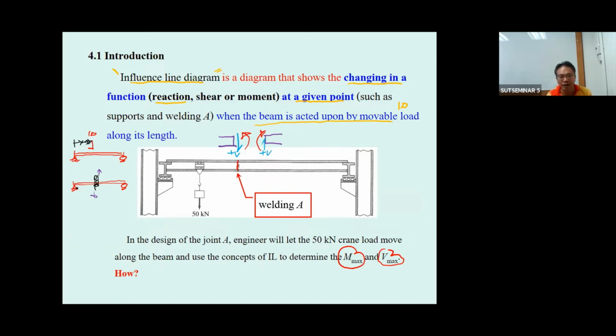So by doing this, this is going to be the pin. Pin is the rotating point. So what you get is the beam going to change shape like this. For this one, it's going to move up. And I should note that even though you release the V, we still have the M over here. So it moves like this with the M still here.